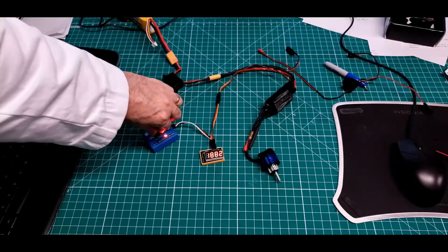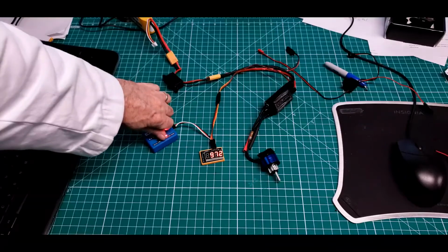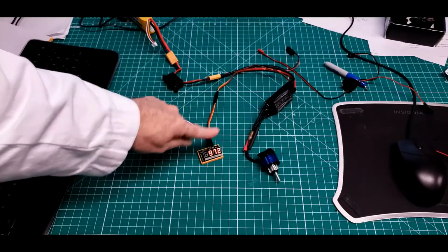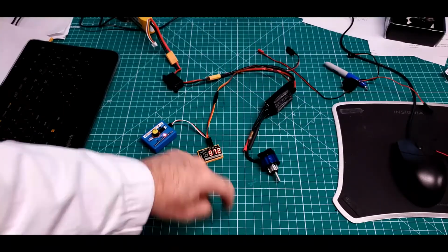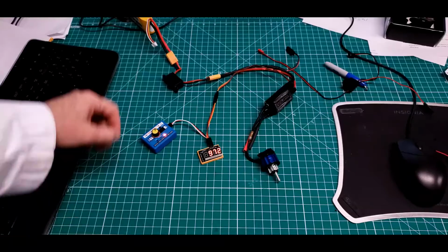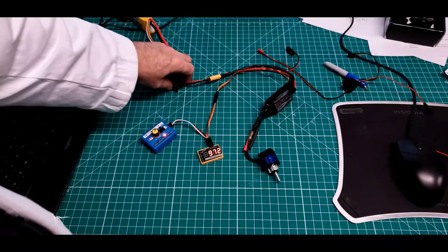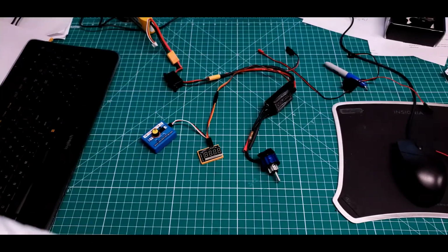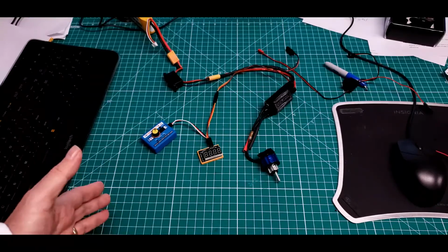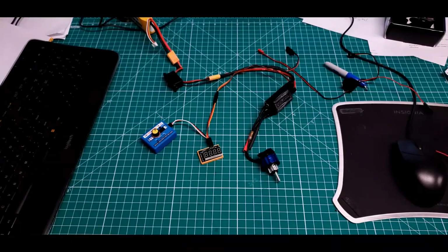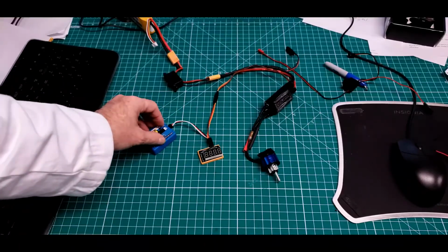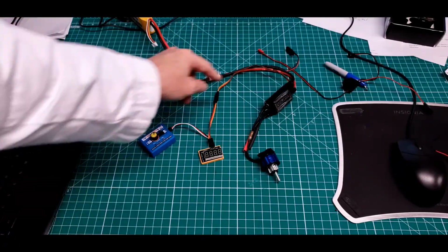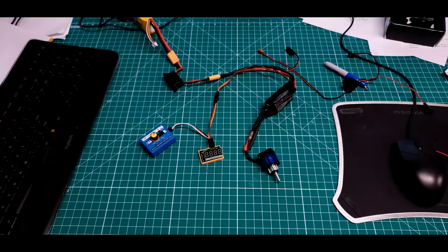Did you hear that signal out of the ESC? And now it gave out another signal when the number was at its lowest. If I turn it back off now, it should be storing those values. When I turn it back on, seeing the throttle isn't as high as it can possibly go, which puts an ESC into programming mode,